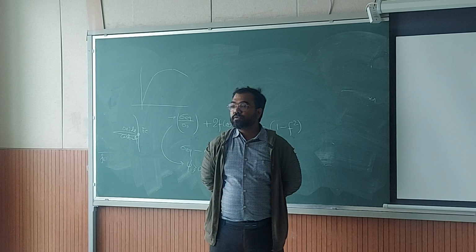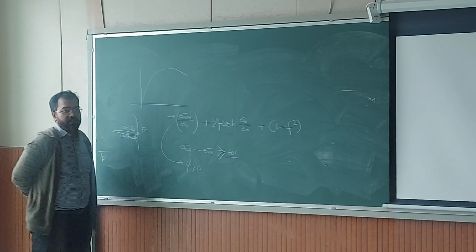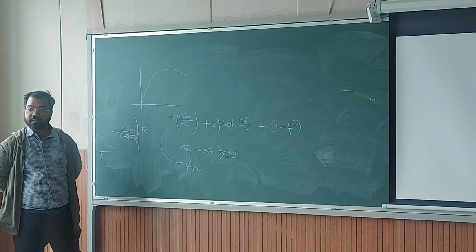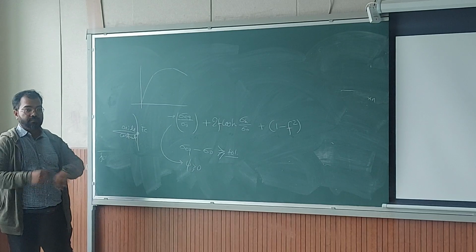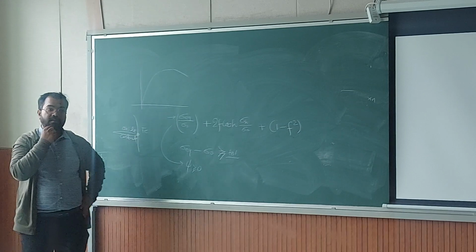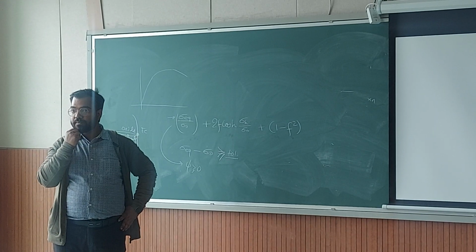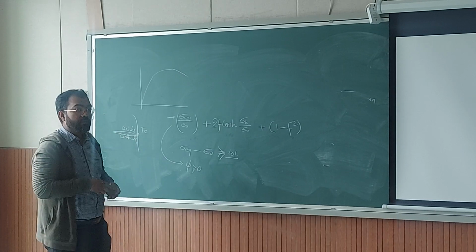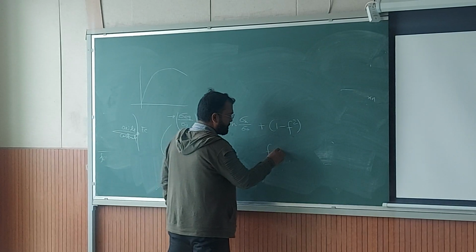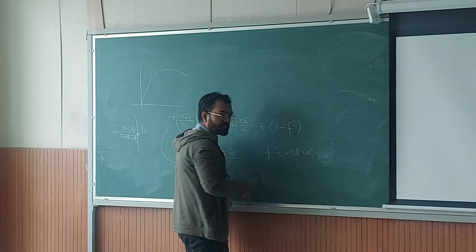Okay, so this is where you have a different yield function which is dependent on a damage parameter. And what is the damage parameter here? F. What is F? Damage parameter. Yes. F is the void volume fraction, the void volume normalized by the total volume.